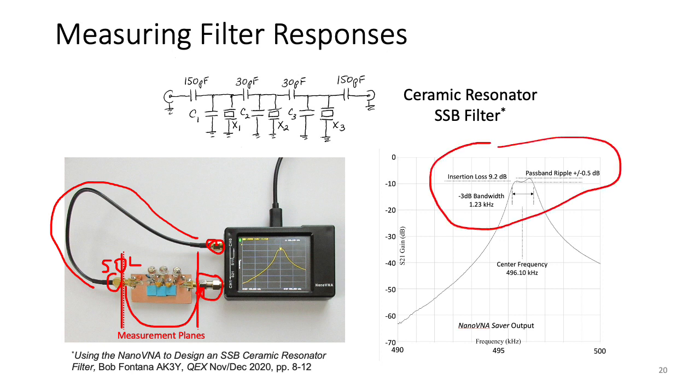This output was performed again using the NanoVNA Saver software, downloading that to a file which is then plotted. You can see the same results here, but it's somewhat difficult to get very precise measurements on this. You can do that with a little thumb wheel switch on the top, but in general, it's nice to be able to use your computer to look at the results more carefully. When you're out in the field, of course, it's more difficult to lug around a laptop, but in general, I tend to like to attach the computer to the Nano and use the Nano as a standalone instrument.